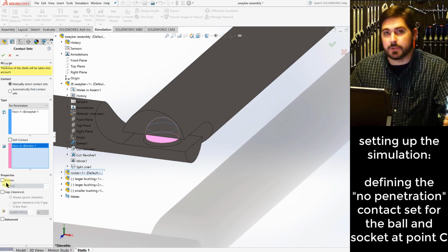I'm not going to define any friction for this one because I don't need to. The other one will be enough to stabilize axial rotation, which in real life wouldn't actually be a concern, but in here it helps if you make it to where things cannot just sort of move because nothing has friction.